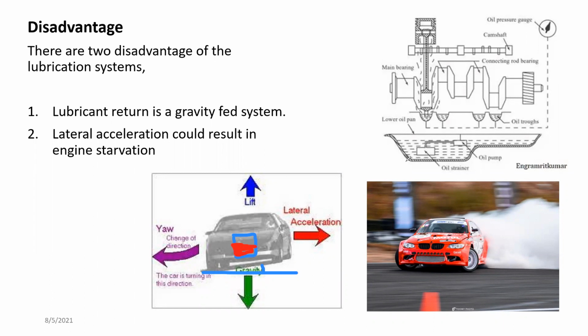But in most cases, as the engine has to be mounted as low as possible, the sump's depth is very limited. So in such cases, the engine could end up having oil starvation or not having any oil. This could actually result in a big problem.